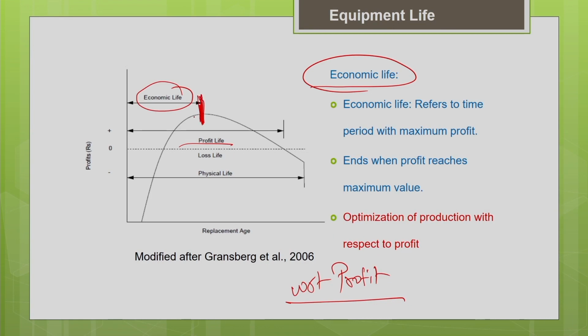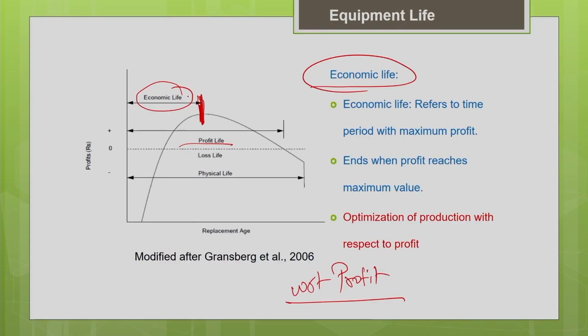So if you want to maximize your profit, it is better to replace your machine at the end of the economic life itself. Before your profit gets reduced due to the increase in maintenance and repair cost, before that itself, replace the machine. Replace the machine at the end of the economic life of the machine.